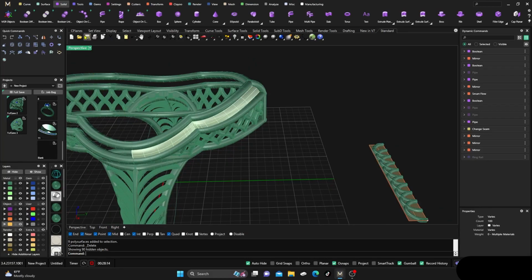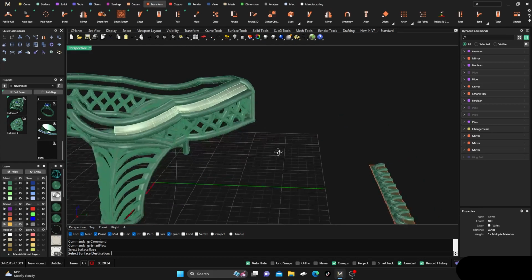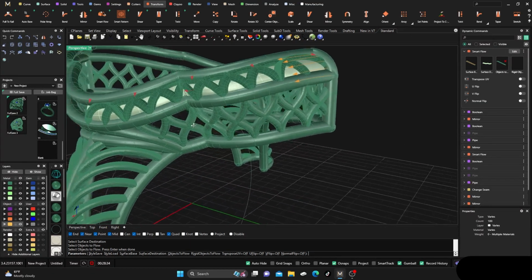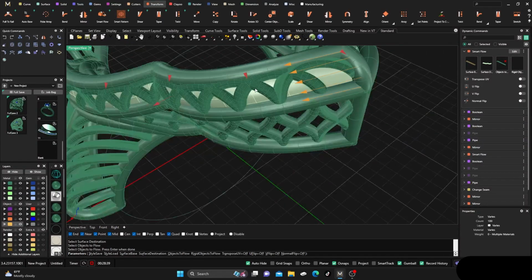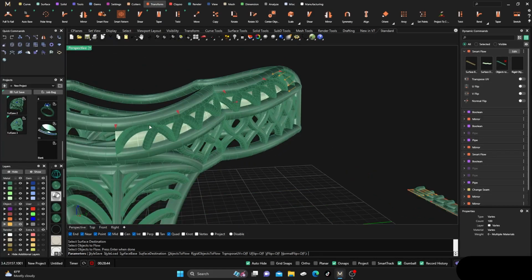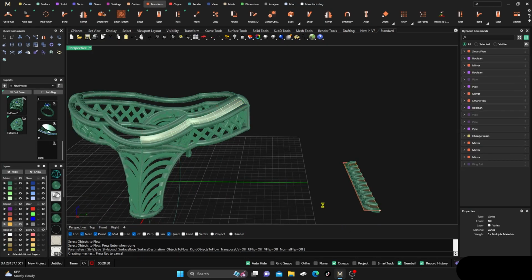And let's do that smart flow again. Transform, smart flow, base surface first. This one. Destination surface, this one, objects, these, and hit enter and see how that flows up there. Yeah, pretty cool. Yeah, it kind of comes up. I should probably not have drawn them back so much. So let's go ahead and hit enter. My history's on, so maybe this will work.